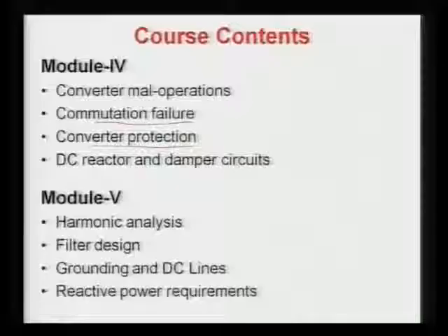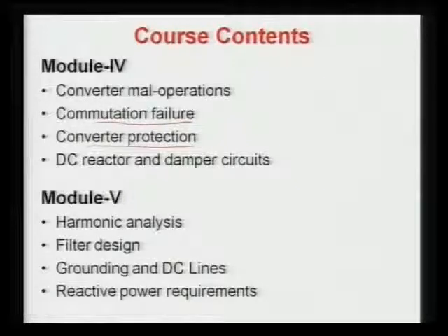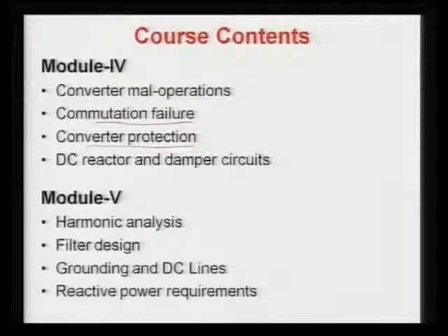Then we will see how to protect the overall converter circuit. We want to protect the converter circuit and our HVDC lines. So we are going for over voltage protection, over current protection similar to AC current, and also differential protection for checking the link differential current. So the complete inverter as well as rectifier side system protection is discussed. Another topic here is the smoothing reactors, basically the DC reactor, which is used to limit the rate of rise of voltage or current, and what the inductance values will be.